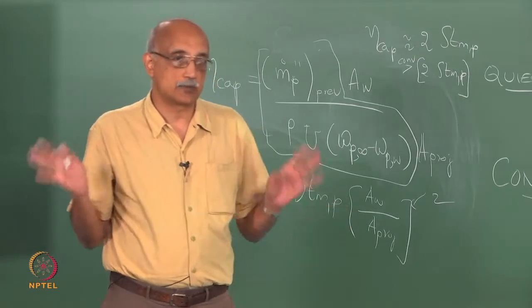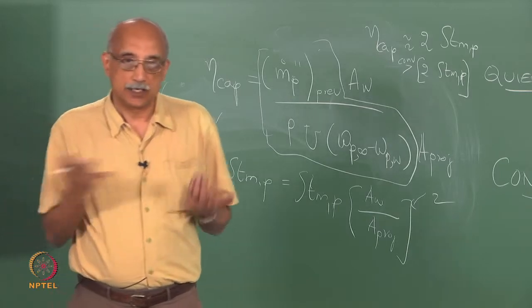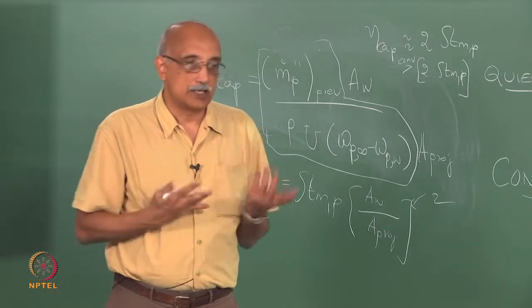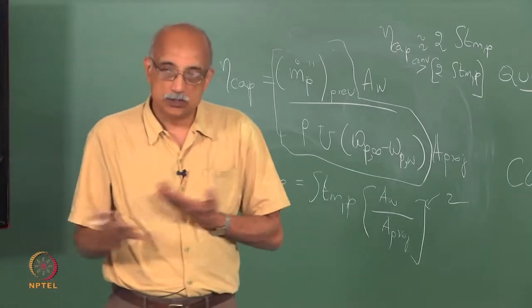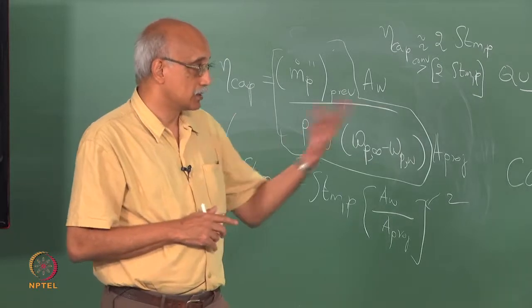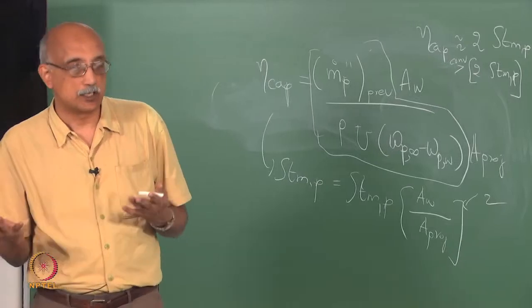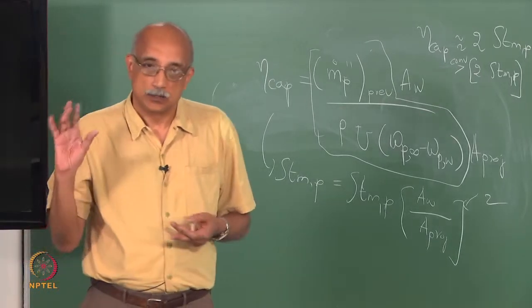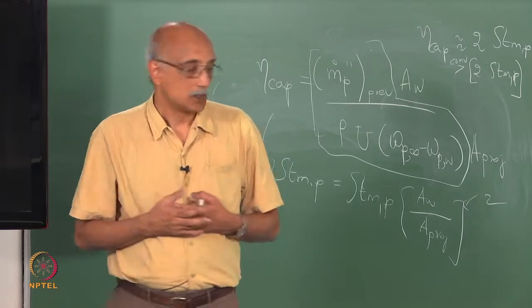The most basic non-dimensional parameter in any flow situation is the Reynolds number. The Reynolds number is a measure of momentum transfer by diffusion to momentum transfer by convection. The second most fundamental non-dimensional parameter is the Schmidt number, which is a measure of the kinematic momentum diffusivity to mass diffusivity.